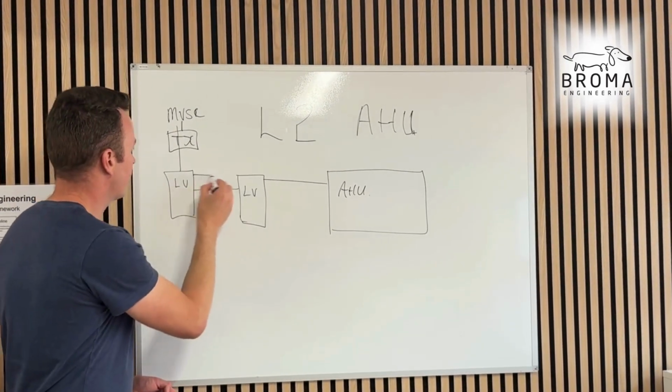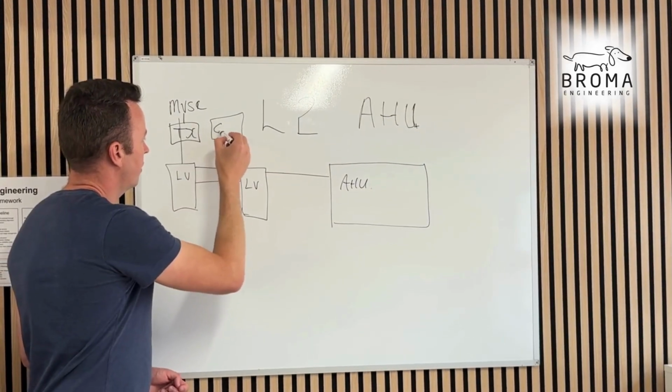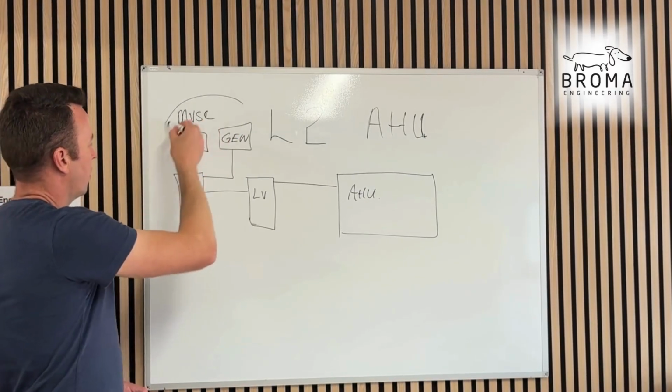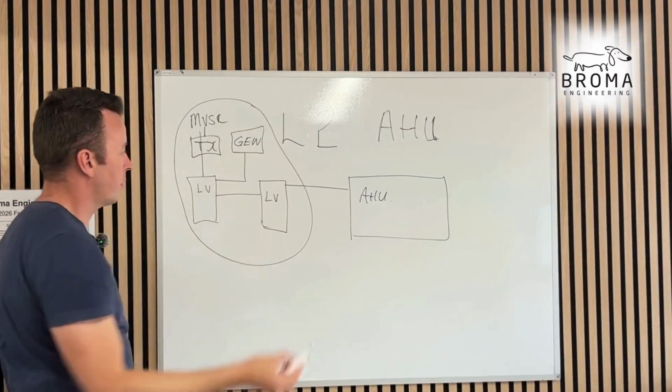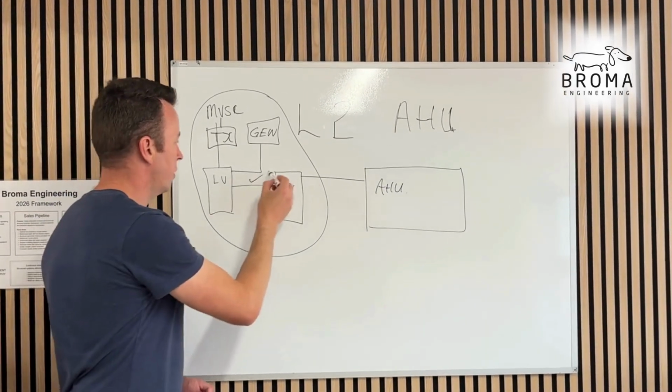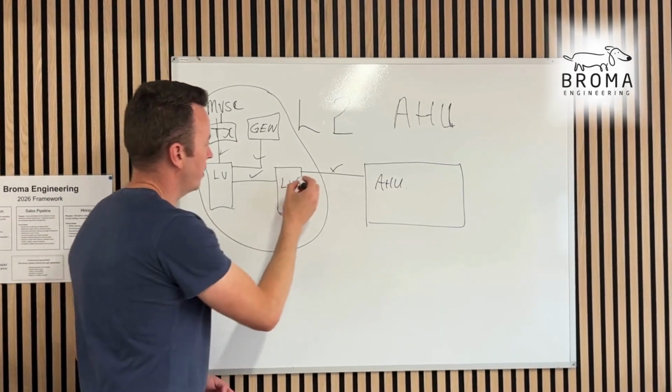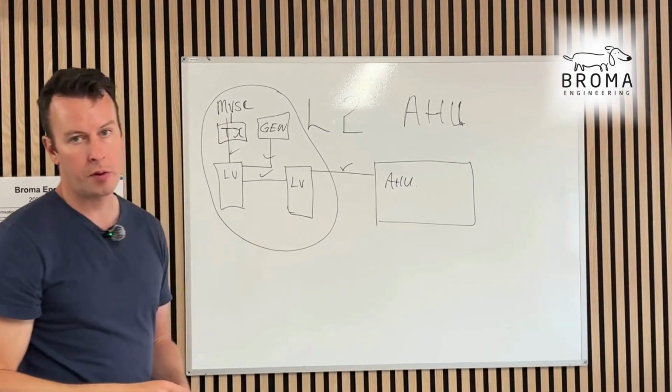And into this you're also going to have a generator. So this is going to have to be complete. All cables tested, power on all the way up to here or here. It depends on the strategy for power on and the switching plan.